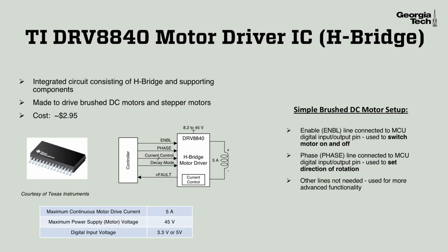Here's a little bit of information about a typical motor driver integrated circuit, the DRV8840 available from TI. So this is an integrated H-bridge circuit, and it's made to drive brush DC motors as well as stepper motors, and it only costs a few dollars, so it's a relatively cheap component. We can see the schematic of how you connect this H-bridge motor driver to a microcontroller, which is labeled just controller in this diagram. So what we do is we connect the enable line to our microcontroller, and that's really going to be used to switch our motor on and off.